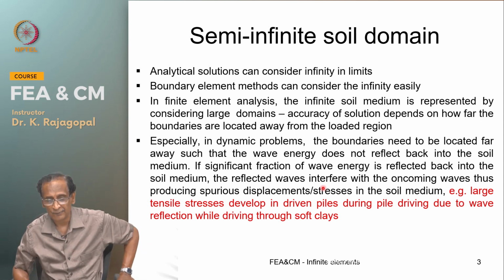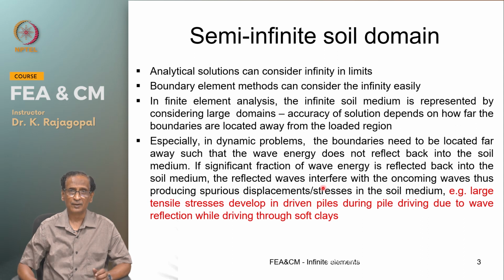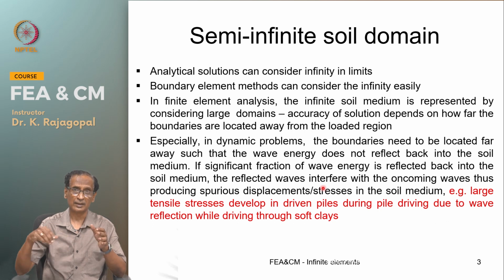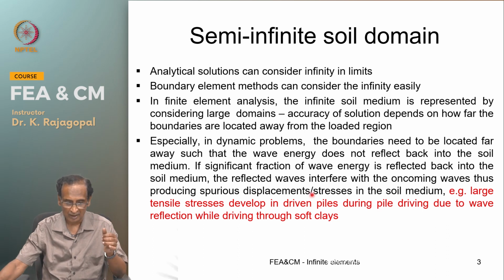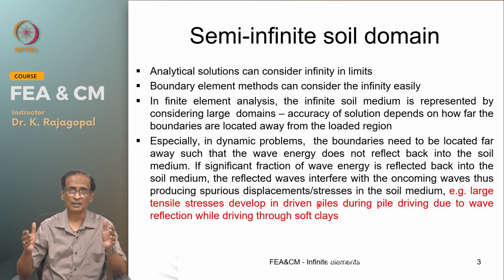And so, if you see the IS code for the driven piles, they recommend a very large percentage of steel, almost 2% of the cross section, whereas for a bored pile it could be just a nominal reinforcement for the normal shrinkage purposes. So, this additional steel in the concrete of the driven piles is because of these extraneous stresses that you could generate.